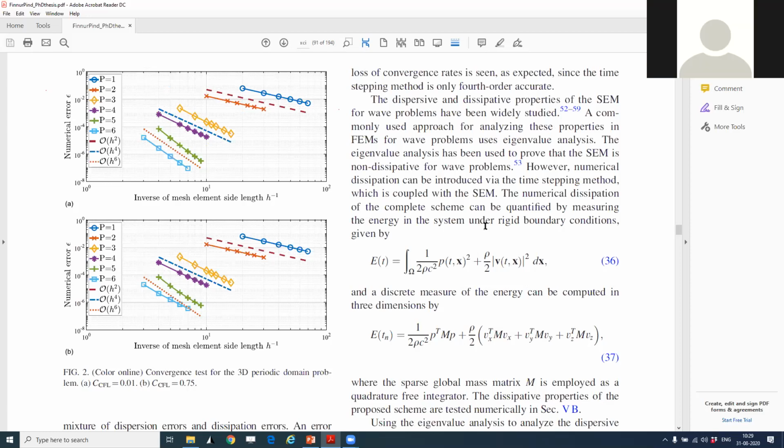But so for this, if you keep the element size fixed and then add higher-order polynomials, are we then adding more degrees of freedom in each element? Yes, which is not shown in this plot. So it doesn't tell the whole story. If you just look at this, you think, wow, obviously higher is much better. But there are these caveats, right? You add more degrees of freedom.